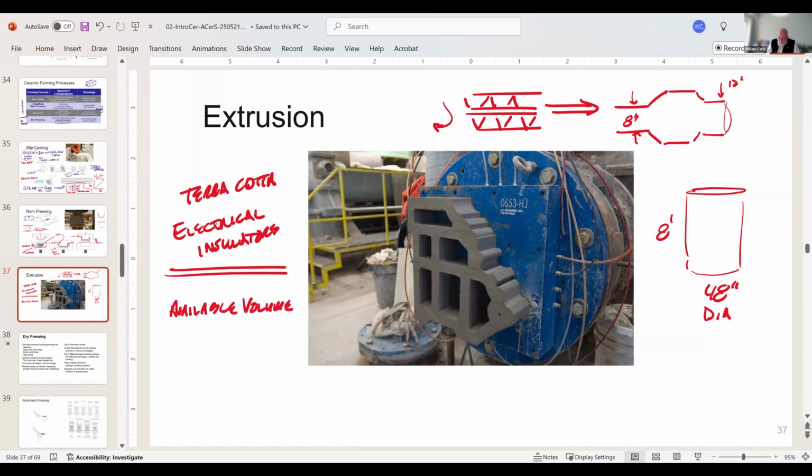It means you need a little bit of excess volume over what is necessary to fill the pores. We take our general rule of thumb of 50% pore volume for a packed body, which is not a bad assumption.